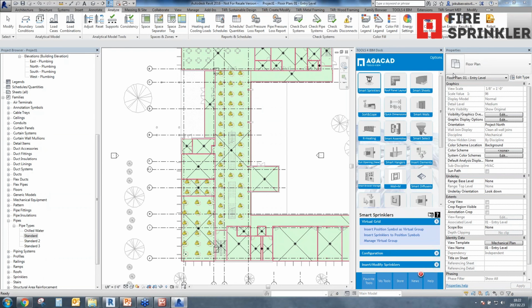Why do we do that? We'll try to do it like this. I feel that you can see my drawings on my monitor. If you have sprinklers, you have a range pipe, and we have a big distribution pipe. So these little pipes that are connecting the sprinkler with a range, we're calling sprinkler pipes. This is a range pipe, and this one is a distribution pipe. So we have to create our three different pipe types with different routing preferences.